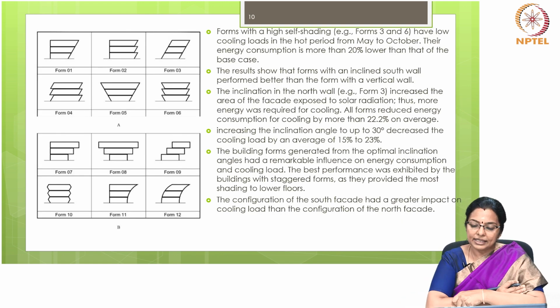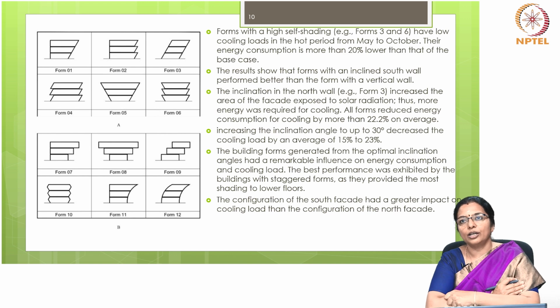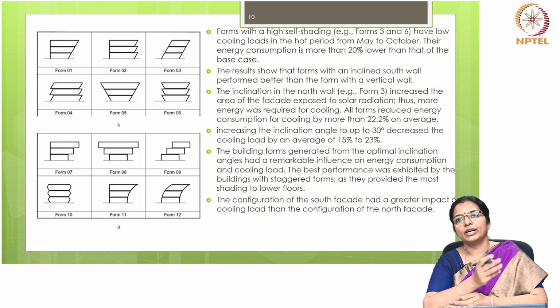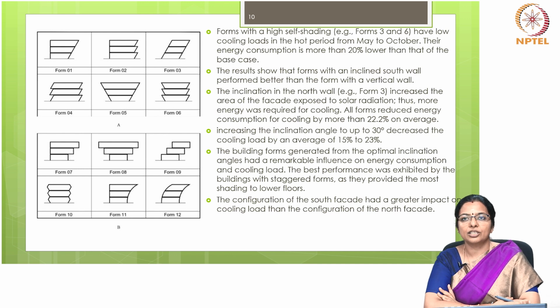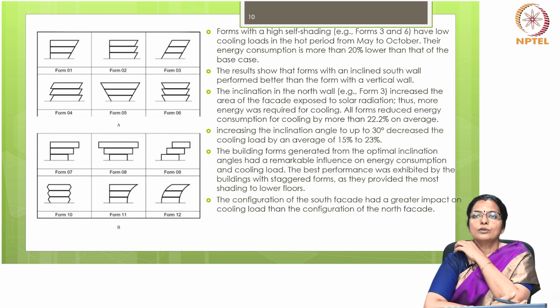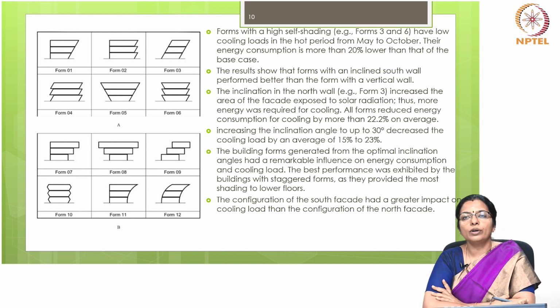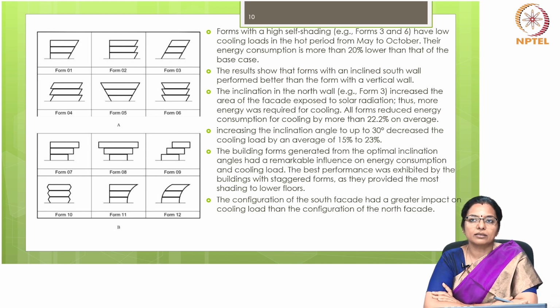Then see, a research was conducted to explore the potential of building forms to improve energy performance and interactions with sun rays. Surface insulation, cooling and heating loads as performance indicators were studied using many methods such as the IESVE Suncast package, Energy Plus engine with design builder interface, and mathematical calculations.